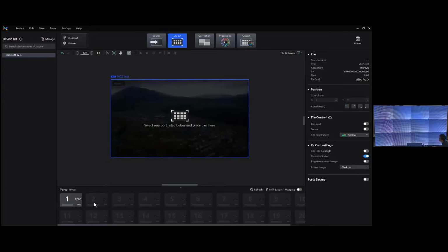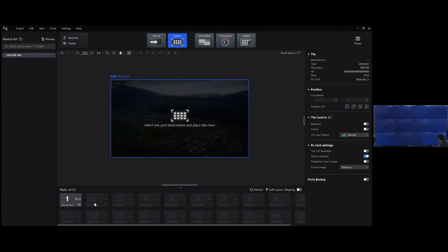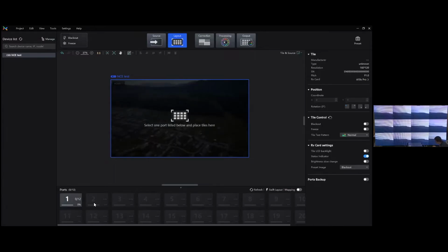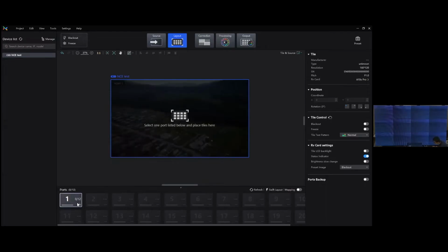That is because the VMP software reads the data information from controllers in real time and directly shows the result for you. So you need not count which port loads which part of the LD screen, because VMP already tells you directly here.